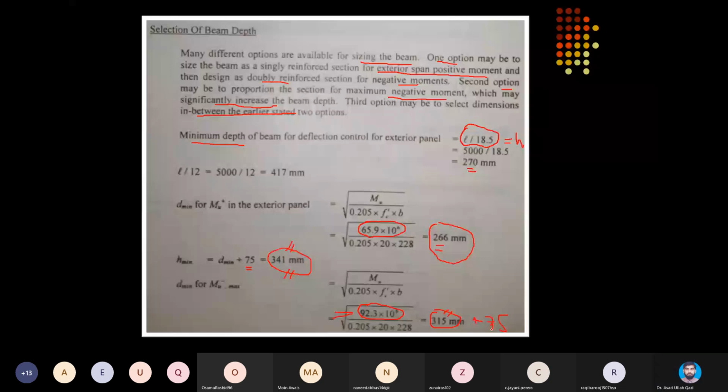So it is quite an unconservative proposal, 3500. So out of them, the least, which is conservative, the minimum is selected, and then it means we have fixed the flange width of the beams, which will be particularly applicable at sagging regions where the flange is in compression. So this BF becomes important.